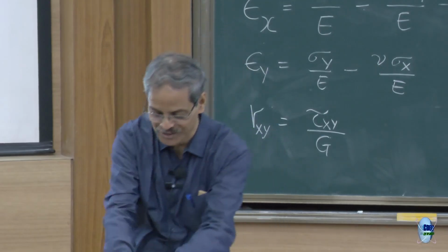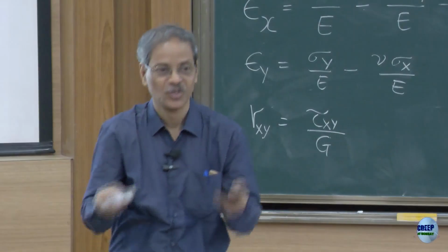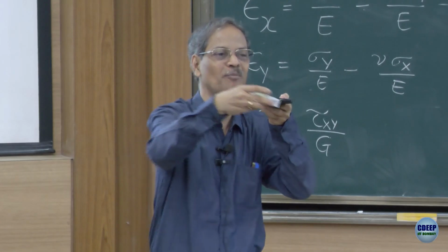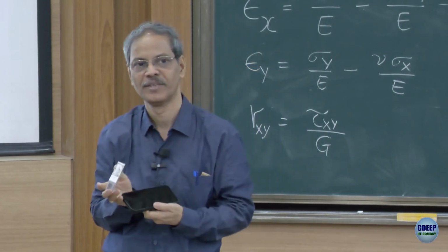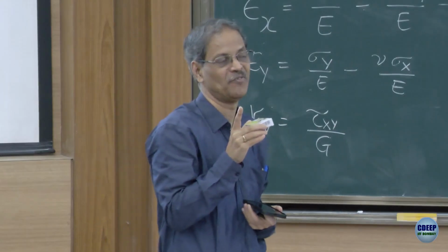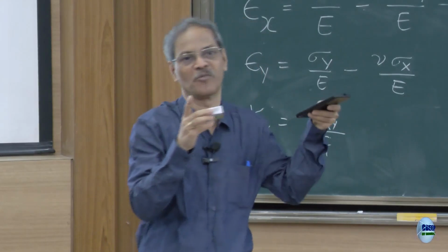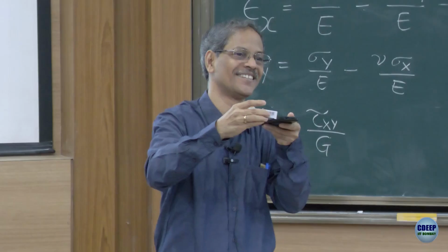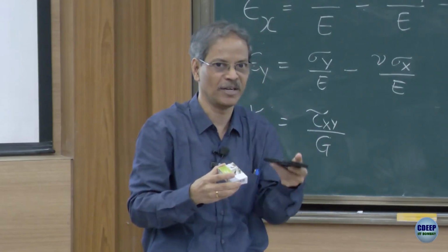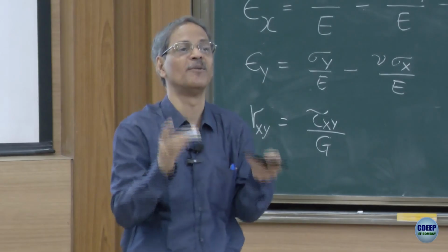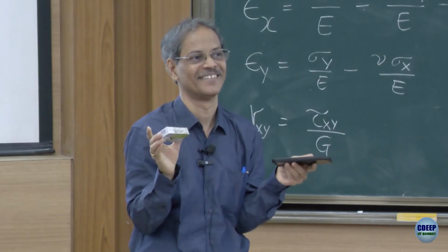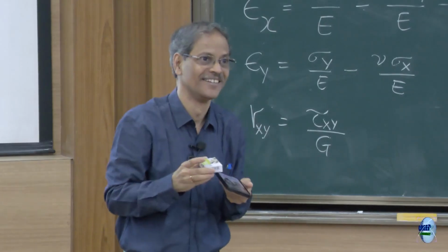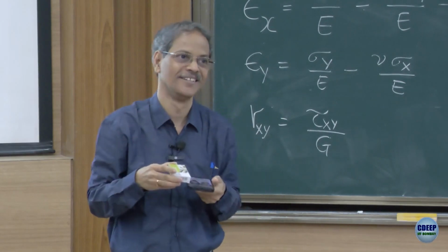But now imagine what happens when two elements in two dimensions come across. There is an infinite number of points along an entire edge. It is not enough if at one point temperature is the same coming from this side and coming from this element. For all the infinite number of points on this edge, whether you consider them to be part of this element or of this element, the field variable has to be the same, right? And then of course, this is only the field variable. You can then ask also about the derivatives.